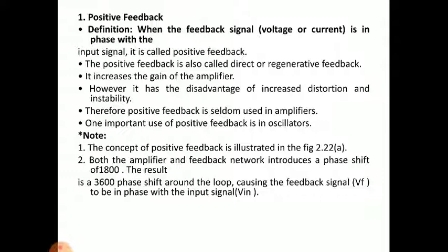However, it has the disadvantage of increased distortion and instability. This is important. These are the disadvantages: increased distortion and instability. That means continuous increasing of gain leads to instability. Therefore, positive feedback is seldom used in amplifiers. Seldom means very rarely.